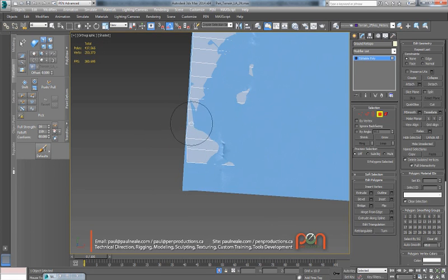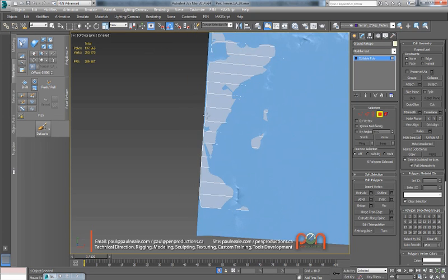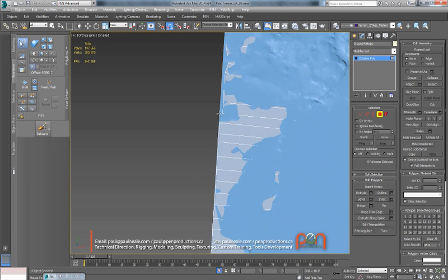You'll see it doing weird things when it goes off the edge. See, as it gets pushed off the edge, you'll see them jumping around. At that point, you might want to move to just the drag tool. It does one vertex at a time, but it'll actually push them up to the edge really nicely, whereas the Conform brush will start getting confused when it hits an edge and doesn't really know what to do.